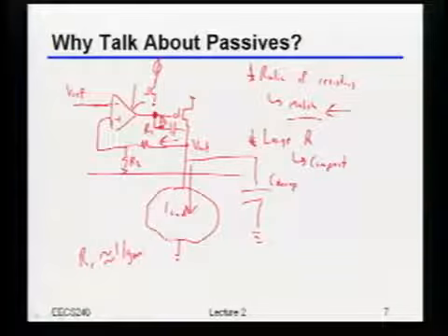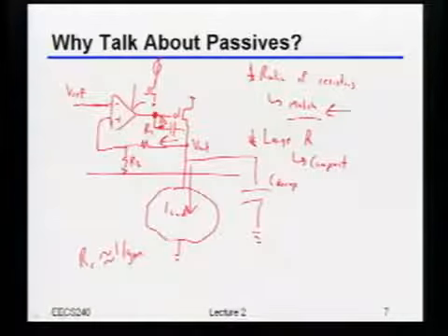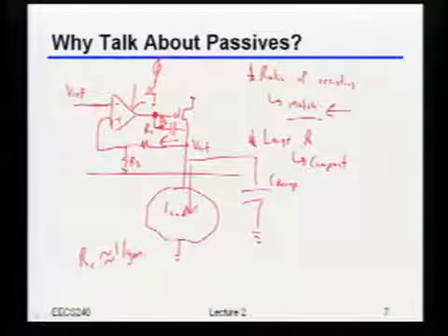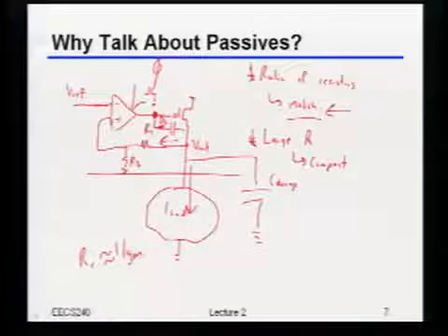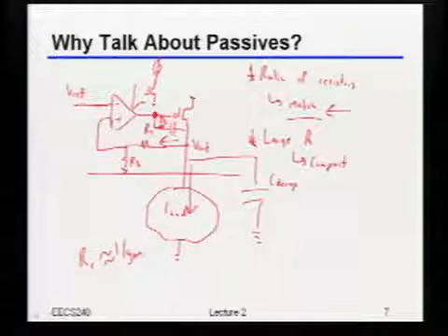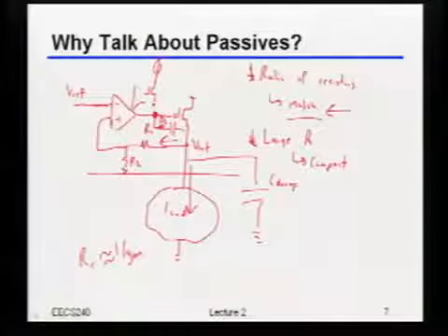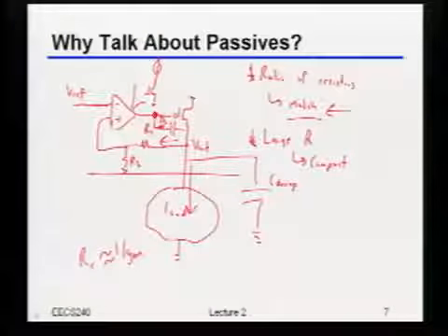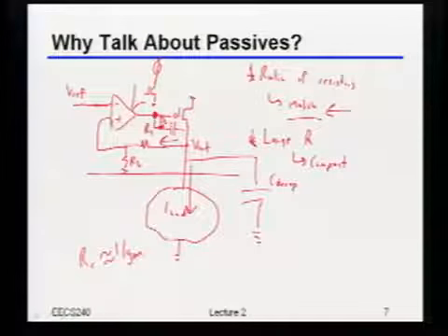Kind of resistivity and materials and things like that. So if I was to really do this in SPICE, I believe you that you could tweak that R to get it exactly to be 1 over GM. What would happen if you actually built this thing and let's say you got 100 of those chips back? What would happen? None of them would fit. Yeah, it's going to vary, right? So some of them are not really going to be 1 over GM. In fact, none of them are going to be exactly 1 over GM.